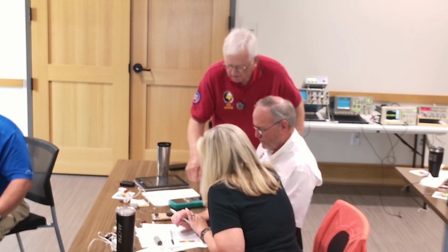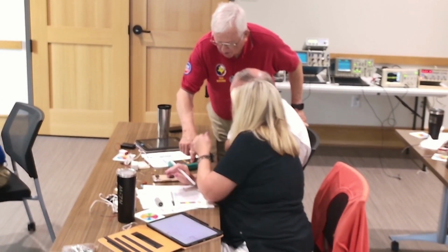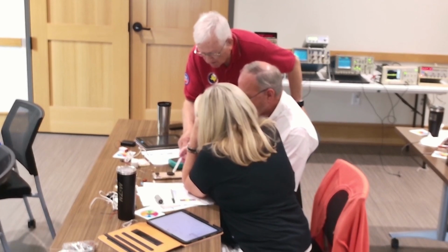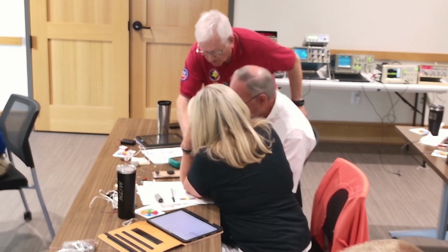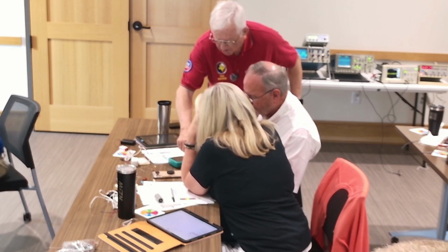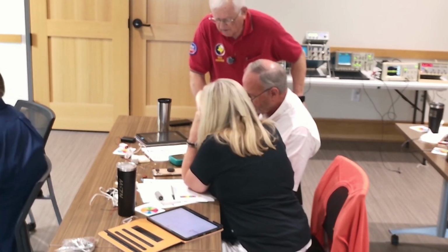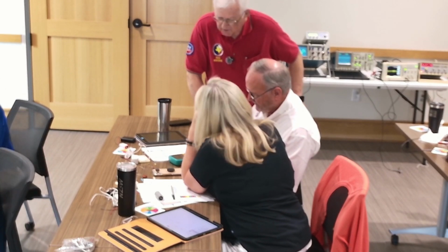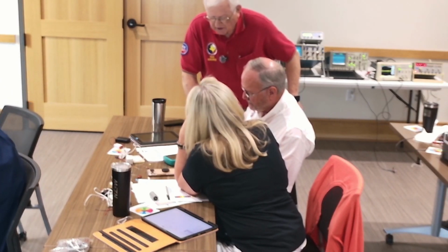Now we're measuring capacitance. Right now it's over here on L, and if we want to go to C, here we go. We'll start at 10,000 microfarads, starting at the highest and working down, backwards. We're at 1,000 here, and this is 10,000 microfarads, which means it's not going to give you a good reading. It exceeds the capacity of the meter itself.